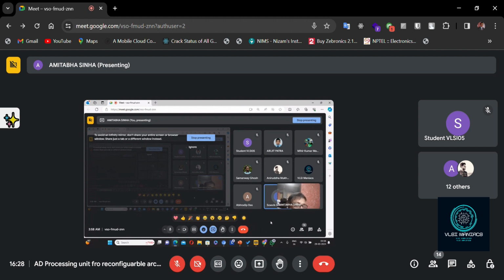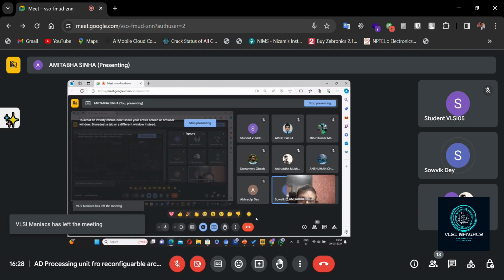That's why we have the Spartan 7 board in our university. When we download the bit stream, we have to select one mode. There are two modes: one is called JTAG mode, and another is called PROM mode. We have to select either PROM mode or JTAG mode. If you select JTAG mode, then the bit streams will be downloaded directly from there. Yes, sir. Okay.